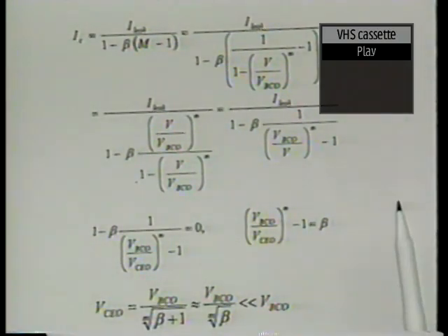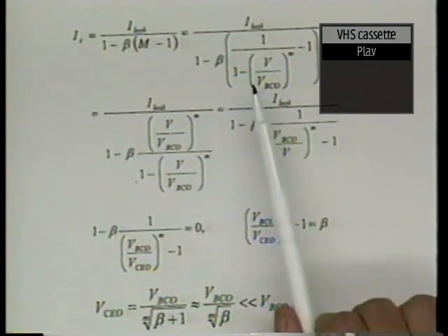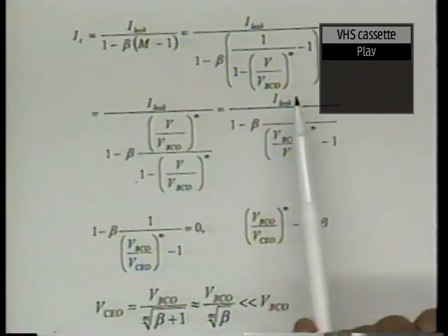So this is the main reason why when the base is open, or when the emitter base is forward biased mainly, then we have a much lower breakdown voltage, all right? Okay, but before we close the loop, let's just finish the mathematics a little bit, because I even gave you some square root relationship. Let's just quickly finish that, and you don't have to follow this through very much. I won't bother you with either.